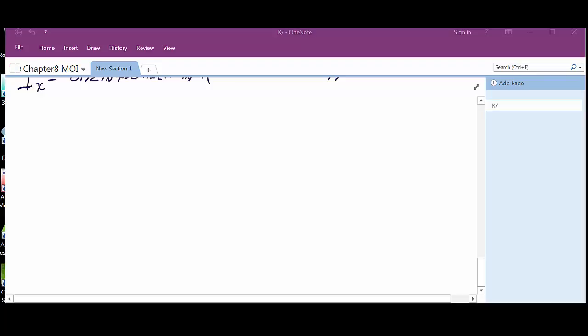The section basically says it's a distance from the reference axis, x or y, at which the entire area is located without changing its moment of inertia. It's the distribution of components of an object around an axis. And it's useful in determining the stiffness of a column.